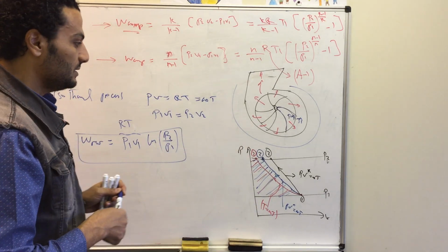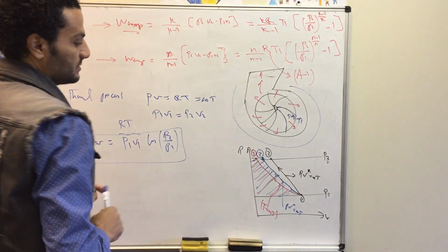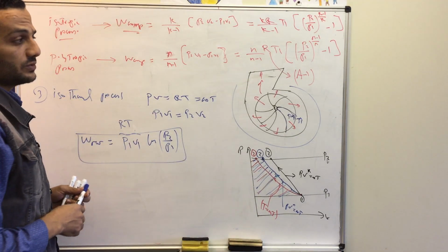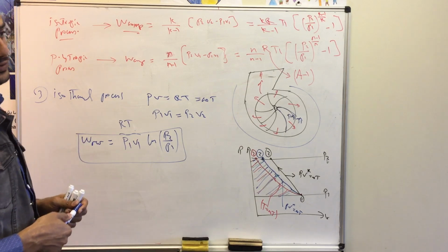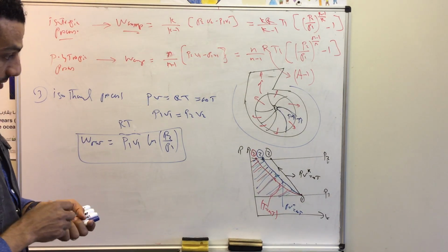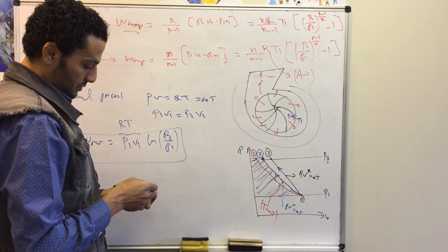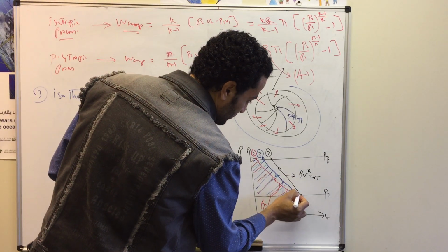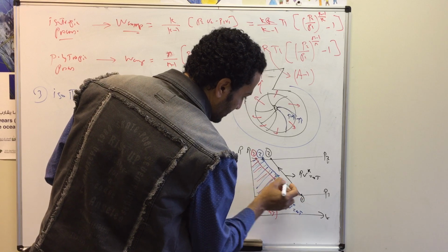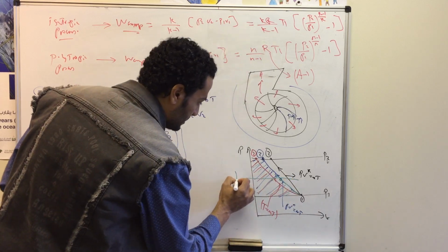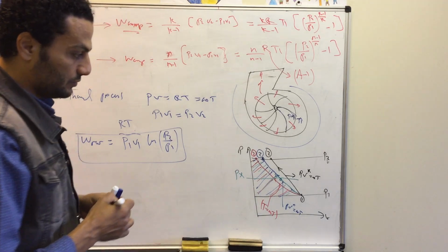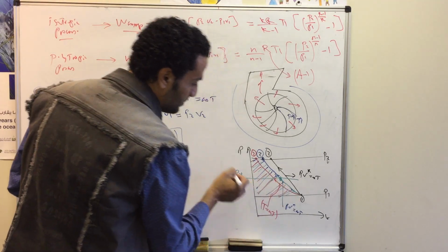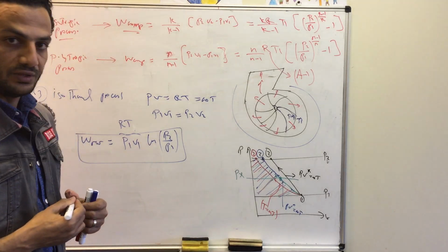Actually, we can achieve a polytropic process, but we need to be very close to the isothermal process, because we cannot actually apply isothermal. What we can do is go through the polytropic process following from point 1, up to an intermediate pressure. Let's call this pressure Px if we have a two-stage compressor. So we go from pressure P1 up to pressure Px in a first stage compression.